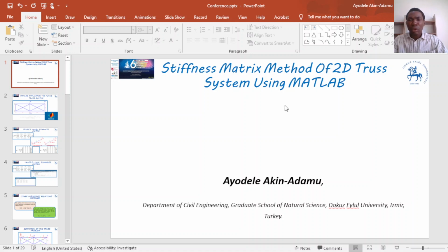In this tutorial, we're going to solve a plane truss system using the finite element procedure by using the penalty approach. But unlike the one-dimensional problem, I'm not going to add the normal large stiffness, which is equal to the greatest value in the global stiffness matrix multiplied by 10,000.